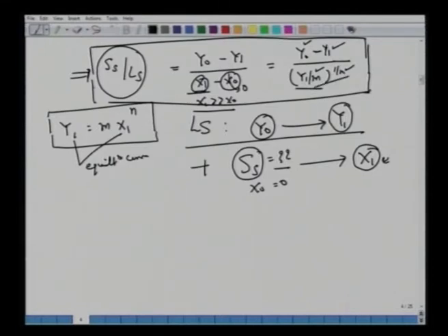We can find out these ratios of Ss over Ls, per 1000 kg of liquid, how much amount of solid is required from here. Okay. Now look at the slope of the equilibrium curve. We have y versus x, and here we have m as a slope and n is the power or index.